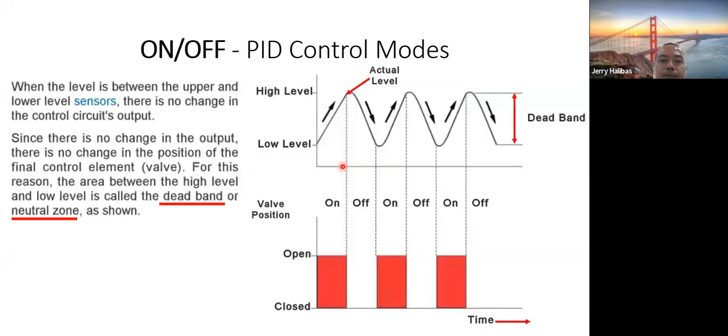Open and close. Now, one of the limitations in an open-close system is that on the graph you can see open and close, open, close. So it is digital. There is a problem with the intermediate area, which is called the dead band. Later, as you advance in the settings of the controllers, you will meet the word dead band. So at least you will understand what is meant by a dead band.